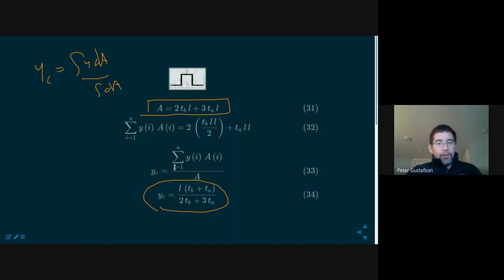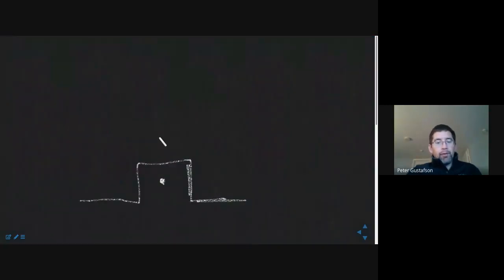And then, of course, David asked the question to get a little bit ahead. He said, well, what happens if it's not through the center? What if it's out here? And I said, well, that's a great question. What we're going to do is move it back and then add a moment, right? So that's what I said. I moved it back so that the resultant was through something called the shear center.